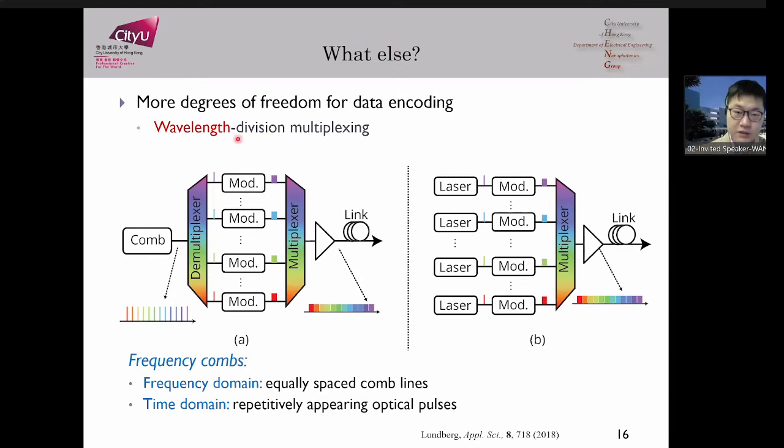And so we previously demonstrated the modulator, and another thing I think we can contribute to this whole system is the frequency combs, right? This is an important concept for wavelength division multiplexing systems. In the old days, you would need many lasers to drive these WDM systems, but recently people found that you can actually make use of a frequency comb, which means you have equally spaced frequency components in the frequency domain, right? And then you can use these different lines as sources for the different wavelength channels.